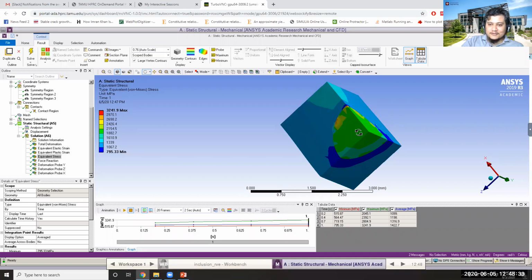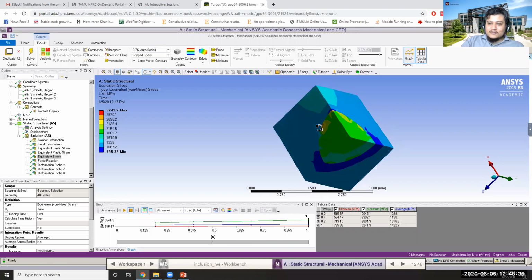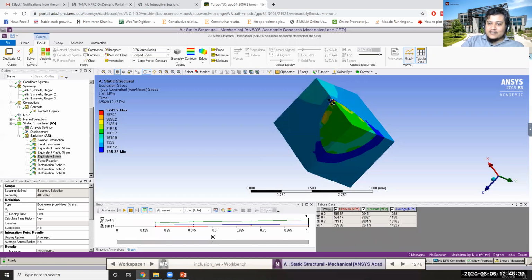Cool. All right, so you can see the distinct division between the stresses and the strains between the two phases. The harder, stiffer phase is taking more of the stresses, but the strains are smaller there. In case of strains, it is the other way around.